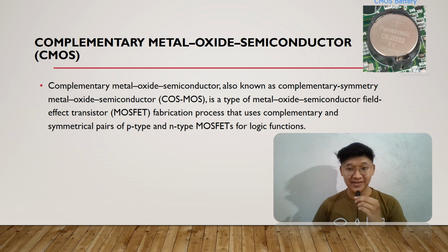Last is CMOS. CMOS stands for Complementary Metal Oxide Semiconductor, also known as Complementary Symmetry Metal Oxide Semiconductor. CMOS is a type of metal oxide semiconductor field effect transistor, or MOSFET, fabrication process that uses complementary and symmetrical pairs of P-type and N-type MOSFETs for logic functions.